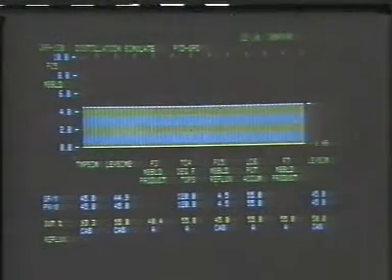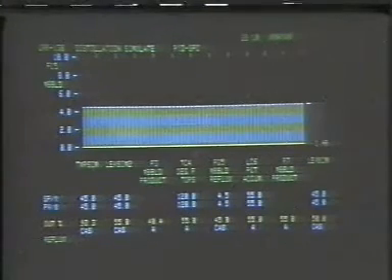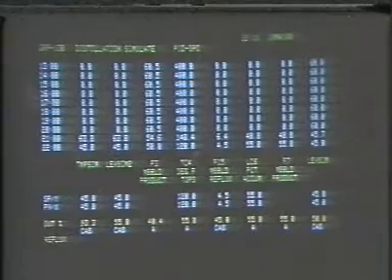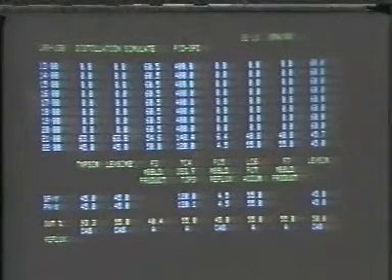reflux rate. This chart shows that the current tower operating conditions have not changed from the previous readings. Had the operator analyzed this data, he might have suspected that the endpoint test was inaccurate because none of the tower operating variables had changed. The most logical thing to do in this situation would be to retest the overhead product before increasing the reflux